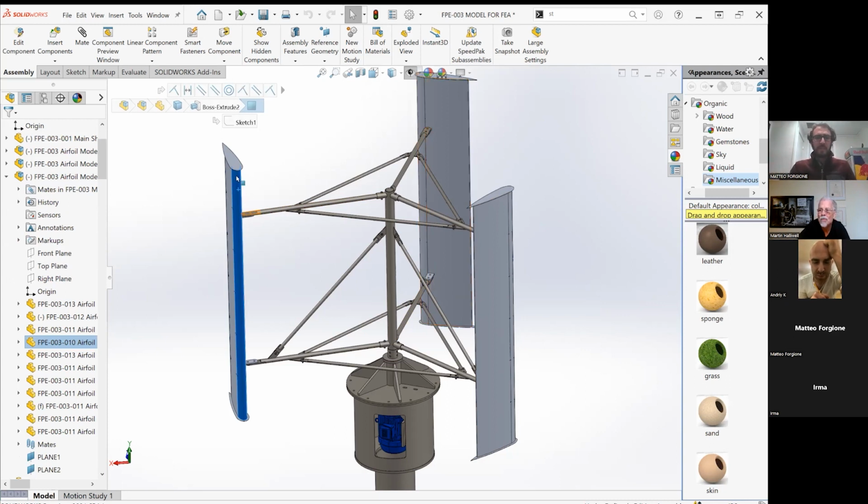Okay. Then because you do have an actual airfoil, there is a position when it's coming around the backside, basically the apparent wind direction, that you actually get a little bonus of some lift as it comes around, where the wind is actually increasing the force in the direction that it's also creating a torque. So the lift force is at certain points, the vector of the lift is actually going in the correct direction and creating a torque as well. So you have this combination of all these drags and lifts fighting against, or not necessarily fighting against each other, but going with each other.